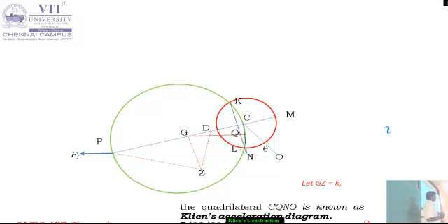So next step, what we have to do? We have to find out the inertia force which will be acting on the connecting rod. Now parallel to OD, from D you have to draw one line. So this is the acceleration. Why we have drawn here? To find out the acceleration which is acting on the point D, we have drawn this. But actually that accelerating force will be acting along the point D.